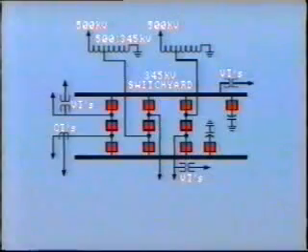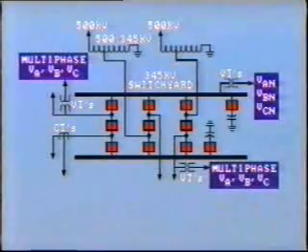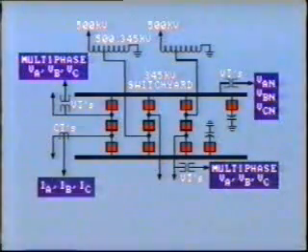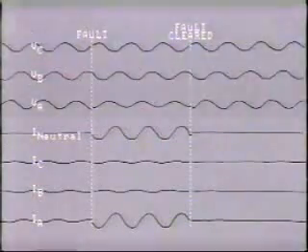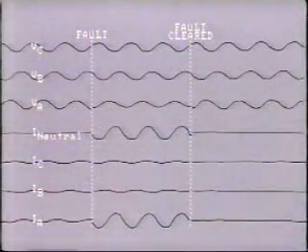Multiphasing comes in handy when we wish to monitor voltages on individual lines in addition to the bus voltage. A common arrangement would be to use a separate channel for each phase to neutral bus voltage, and then multi-phase selected line voltages. It's also important to look at phase current in each transmission line. The current traces can then be compared with voltage traces to confirm which phase or phases were faulted.